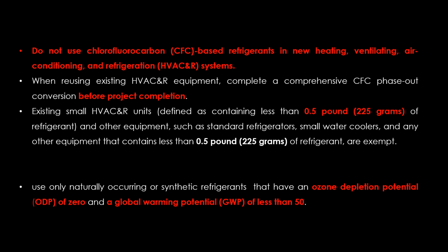completion. Next case, if you are using existing small HVAC and R units, also defined as containing less than 0.5 pounds, that is equal to 225 grams of refrigerant, and other equipment such as standard refrigerants, small water coolers, and any other equipment that contain less than 0.5 pounds or 225 grams of refrigerant are exempted. So these 3 points come under the first prerequisite, fundamental refrigerant management,